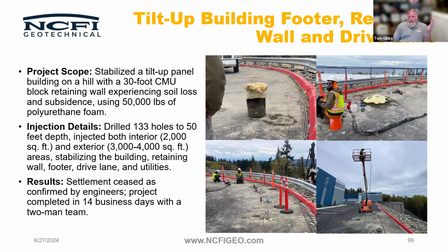So if you're trying to use a bucket on an excavator to dig down beside the structure or whatever, and you've got foam in the way, you're going to want to cut it to try and get it out of there. You'll start pulling on the whole mass, and potentially pulling the whole mass out from underneath the footing if you used an excavator to try and excavate down beside it. But the short answer is yes. You just got to be careful how you're doing it.